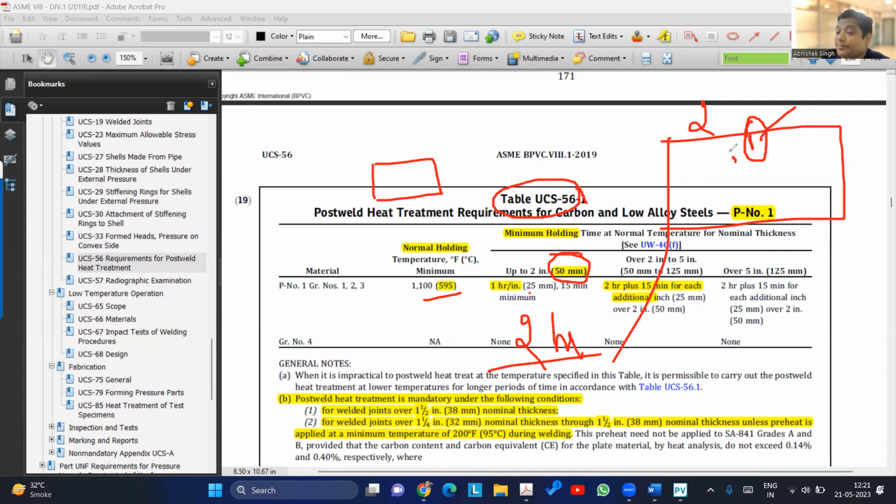So if I have to do a post weld treatment for the same material, I'll take a coupon and we do the heat treatment. So now we know that at least one repair may come. So some material may see PWHT twice. So we may decide two times or three times we'll do the heat treatment of this coupon and then test. This is called a simulation test coupon. So we'll simulate the heat treatment and we'll test it to ensure that properties are still met.